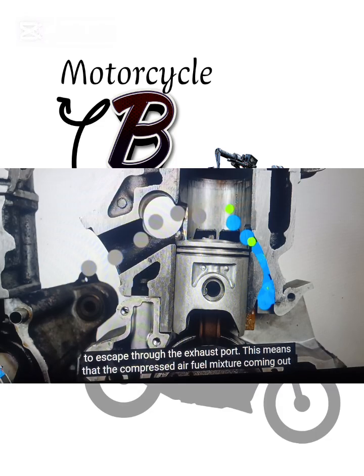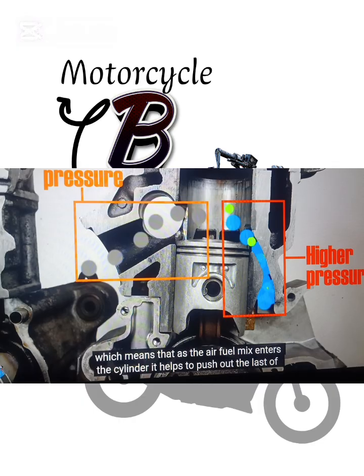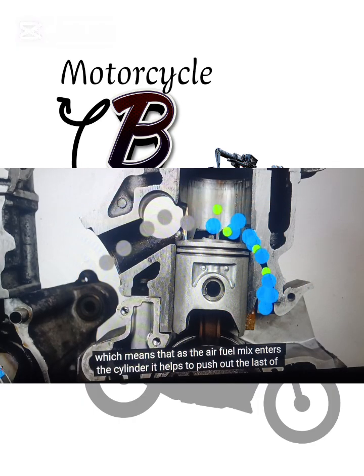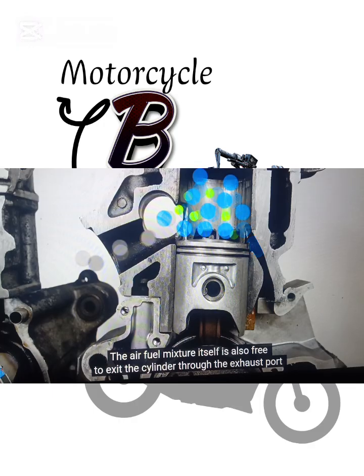This means that the compressed air-fuel mixture coming out the transfer port is actually at a higher pressure than the remaining exhaust gases in the cylinder, which means that as the air-fuel mix enters the cylinder, it helps to push out the last of the remaining exhaust gases. But as you can see, our exhaust port is still open. It's not blocked off by the piston, which means that the air-fuel mixture not only pushes the remaining exhaust gas out the cylinder, the air-fuel mixture itself is also free to exit the cylinder through the exhaust port.